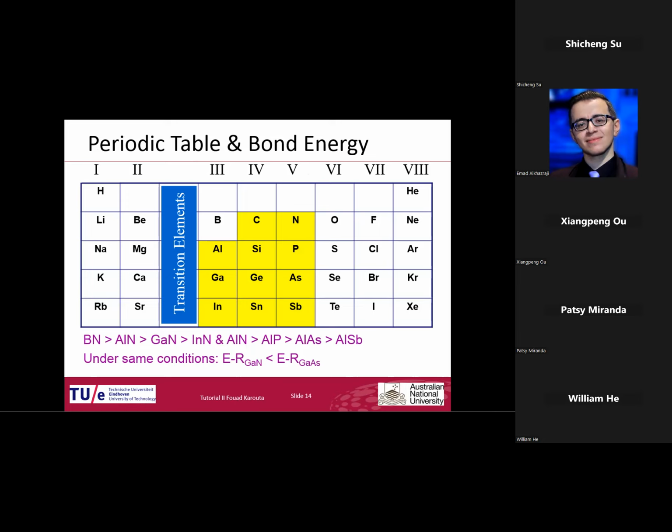Nevertheless, when you are etching silicon, you need to break these bonds to make the silicon free to react with the fluorine gas, for example, and form silicon tetrafluoride, which will be volatile during the process. So if a material has a high bond energy, then you should expect the etching rate to be lower. It won't be very high.